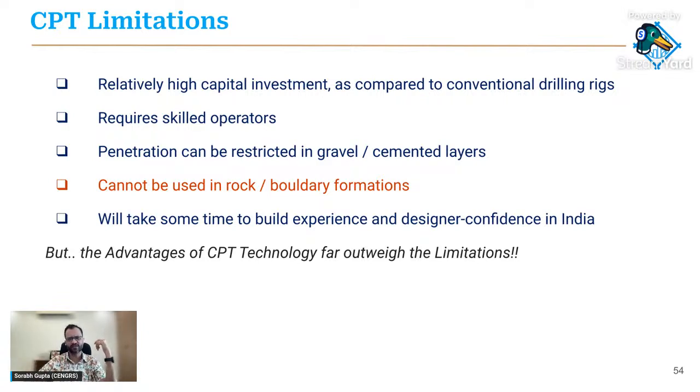It also requires skilled operations. But possibly the largest limitation of CPT is that it works in soil. It does not work in hard strata such as gravel and cemented layers or rock or boulders. Obviously, because it's a push system, it's a push test. If you have a rock or boulders, the cone will simply hit the rock and stop. It can't push beyond the rock.